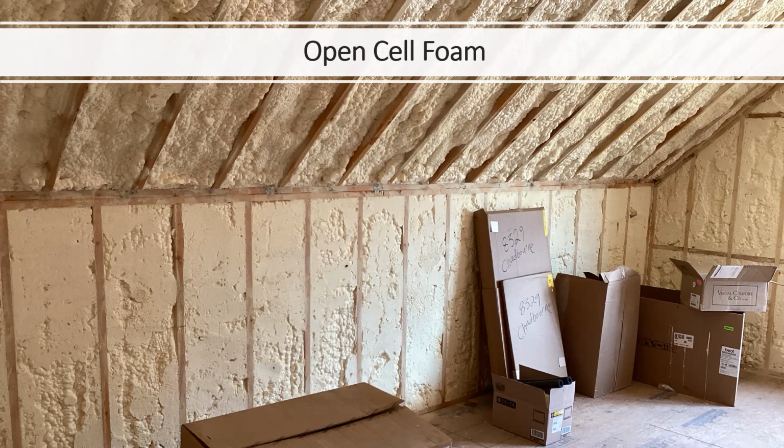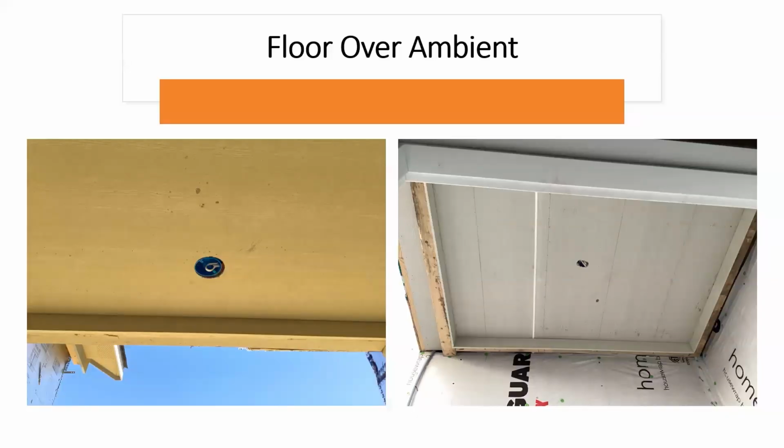But again, listing it as grade 2 is another way of saying it has less R value, because anything less than grade 1 diminishes the listed or labeled R value. So if I said that's 19, but it's grade 2, it's really going to list it less than that. That's going to change the model, and it may or may not fail the model. And that's how it continually starts to work with failing the model, or making sure that it passes.